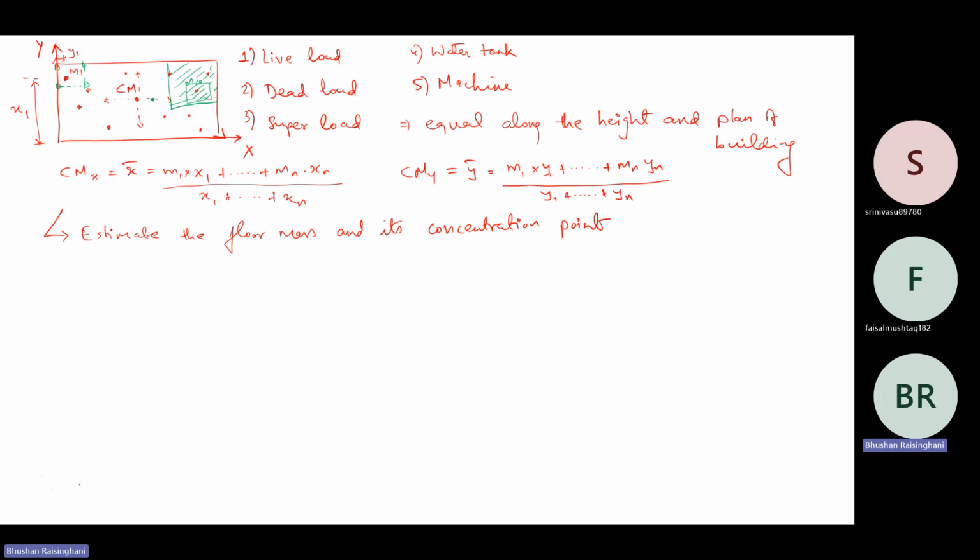However, the understanding is not clear for all, that how to apply these things, in what manner, and how to regulate torsional irregularity and bring it to the practical level. Okay, so that is what we are discussing in this particular session. This is the basic theory and your practical understanding. I have mentioned the loads and their distribution across the height, what is a rigid diaphragm, what is a flexible diaphragm, which the code has already mentioned and I have also addressed. The aspect ratio is also part of your consideration.